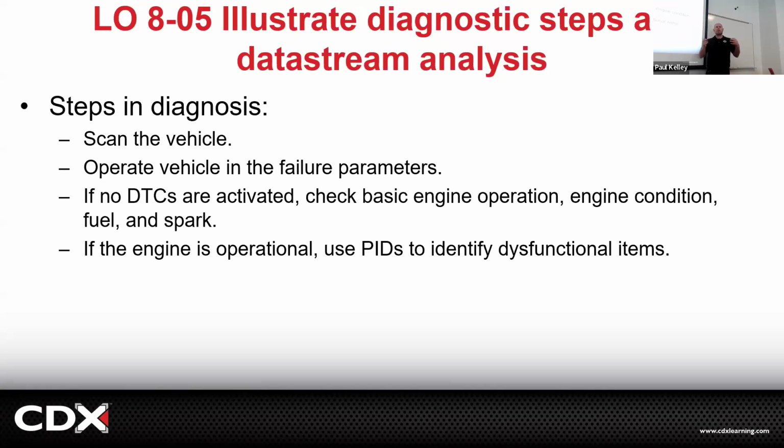And if it's a loss of power, like I hit the gas and it's kind of like, whoa, but it doesn't really go, I'm thinking maybe it's starving for fuel. And I would look at the fuel trim PID, and that would tell me a lot. You don't really have to know everything about that yet. We're doing an overview on how you would proceed with diagnosis.